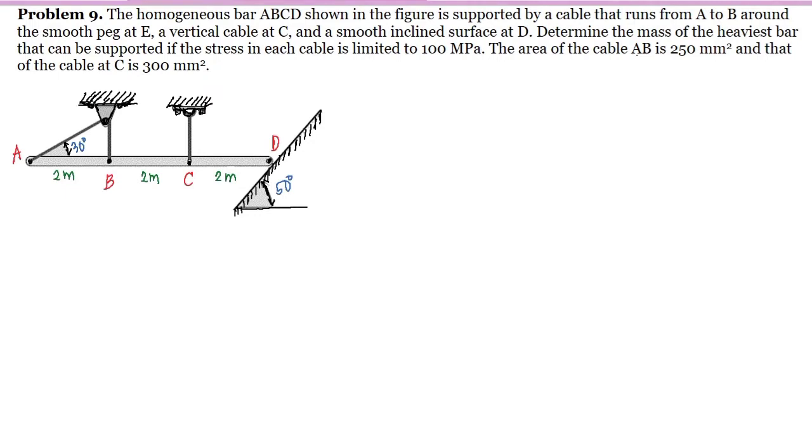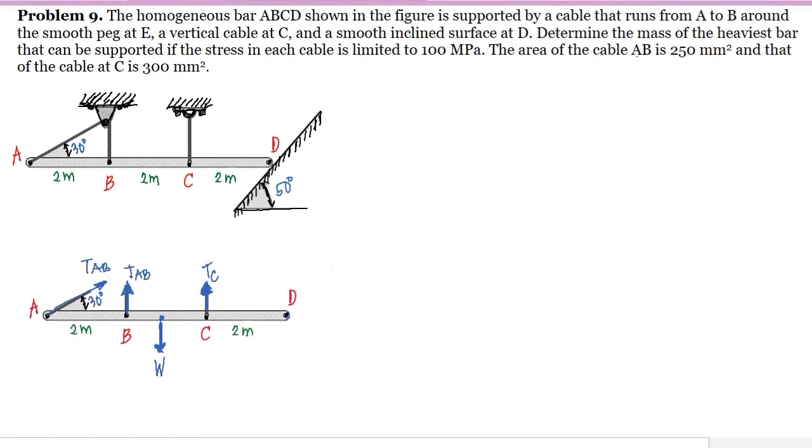So, first thing na gagawin natin dito is to draw the free body diagram. If we are going to cut this cable here, we will expose this tension AB.